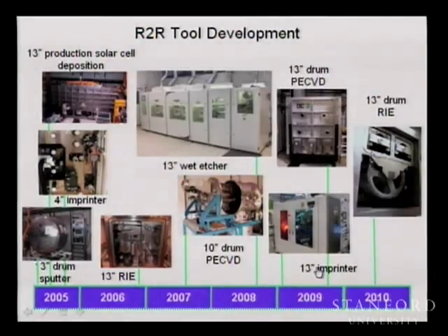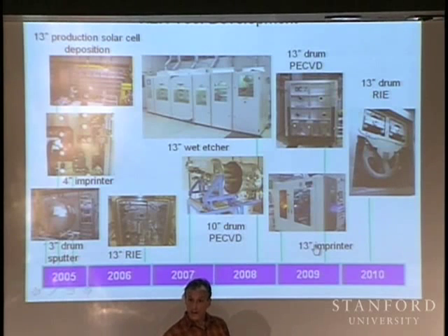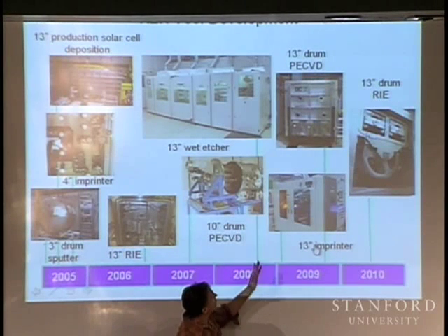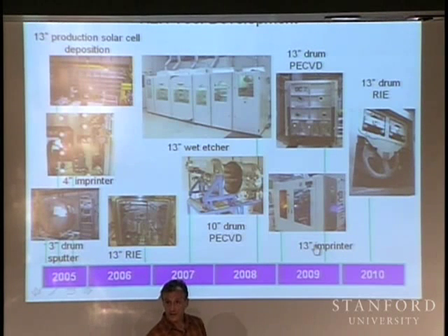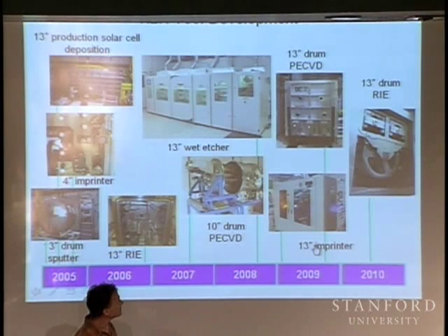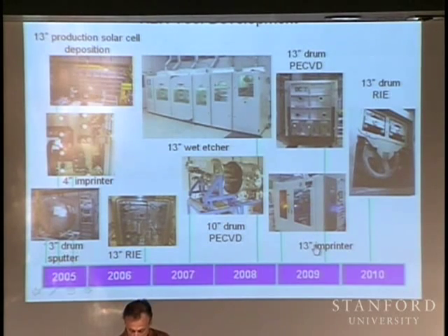Is that in the vacuum? No, this is not. It's in a HEPA filtered environment. This system here, you can see, we open it up, we thread it all up, and once it's threaded, we close it up and start the HEPA filters. That condition cleans up the surface, and then we expose the clean part of the web through the process. That's running at atmospheric pressure? Yes, that one is. Real time? That was real time, yeah.